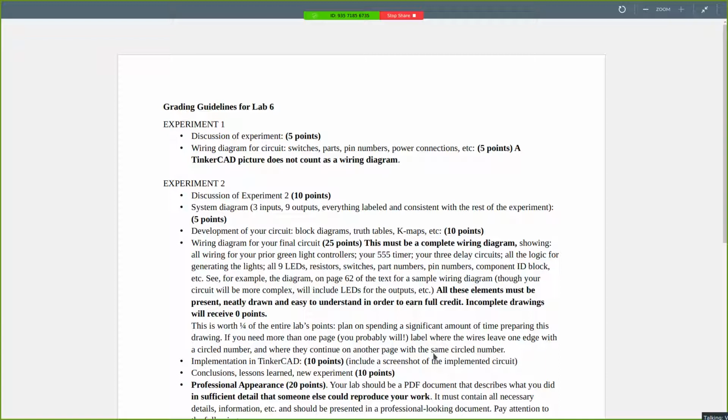Just curious about the Lab 5 experiment too. So I had it go from 0 to 9 and back to 0. And it stopped counting. Is that the end result that we should get, or was it supposed to keep counting over and over again? It should keep counting, but as I said a while ago, it tends to hang up. The circuit that I showed in the beginning of class does go back to 0 and continue counting seamlessly. But I've also had that circuit hang up on me. And it seems to be some sort of issue in Tinkercad.